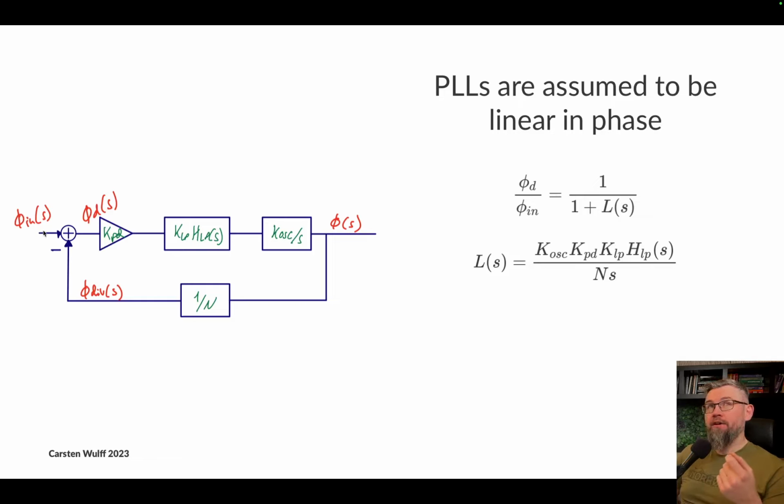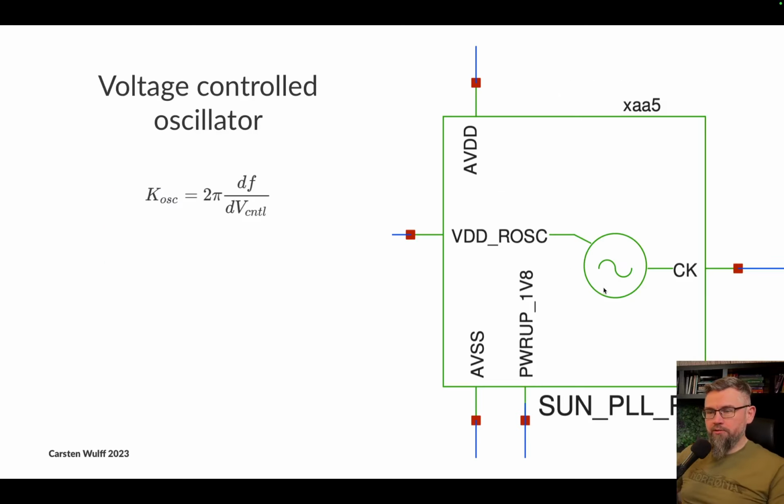So you can't make an infinitely precise clock, but, well, you can buy temperature controlled oscillators that maybe have a few ppm change, but on a chip with components that vary all over the place, you can actually make extremely precise frequencies, extremely precise relationships between the output frequency and the input frequency, because you have infinite gain. And that's cool. Let's go into the blocks a bit.